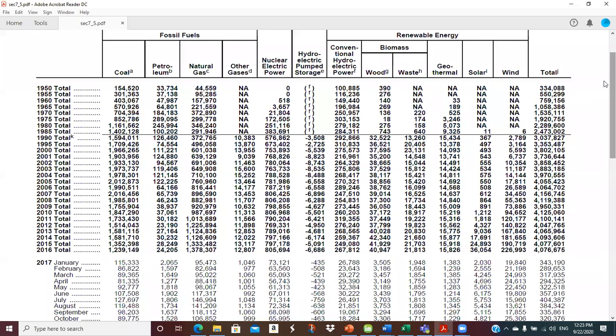There's a lake bed. And so at night, when power's cheap, they pump water up and fill up the lake. And then about 10 o'clock in the morning, when power prices go through the roof in the summertime, they open up the valves and the water falls down through the turbine and they generate electricity. But overall, it uses more to get it up there than they get back when it comes down. But the price when they pump it up there is small, and the price when it comes down is big. And so they make money. So that's pumped storage. And then conventional, that's just the dam.